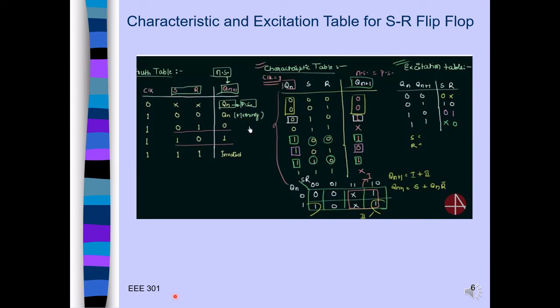Okay, so now this part is very important. We'll discuss the truth table, the characteristic table, and the excitation table. The truth table we already know from flip-flops or latches. Say for the SR flip-flop, we know at the clock edge, if our input is 0 0, it will be no change, or memory. 0 1 gives next state 0, 1 0 gives next state 1, and 1 1 is invalid for the SR flip-flop. So this truth table will be helpful to get the characteristic tables.